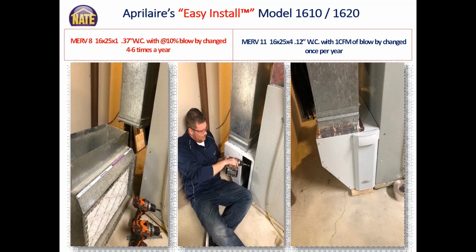These are pictures from one of the training installs we do. All of our tech support people install all of our products. Here you can see removing the 1-inch filter and its transition, and then sliding into that same space with just a little bit of cutting of that return drop. You can see we've just had to stub it out to have it match up with the top of that right angle easy install cabinet.